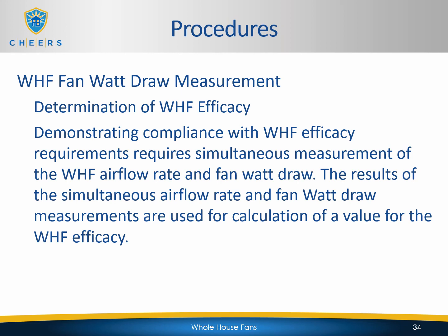Now that we have our airflow value and our watt value, we'll need to determine the whole house fan efficacy. Demonstrating compliance with the whole house fan efficacy requirements requires simultaneous measurements of the whole house fan airflow rate and fan watt draw. The results of the simultaneous airflow rate and fan watt draw measurements are used for calculation of a value for the whole house fan efficacy.